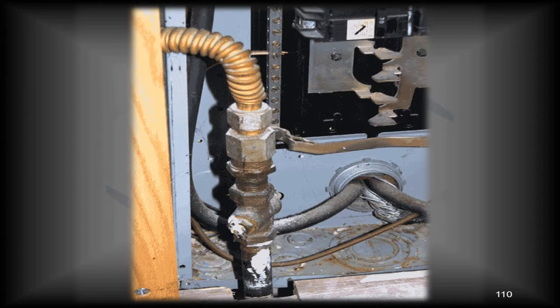Now, what do we have going on here? Notice we have no cover on this box. Everything is exposed inside of there. Because of no cover, and that's a gas pipe there, we have the potential of a leak, possibly followed by an electrical spark or arc, leading to all kinds of not good.